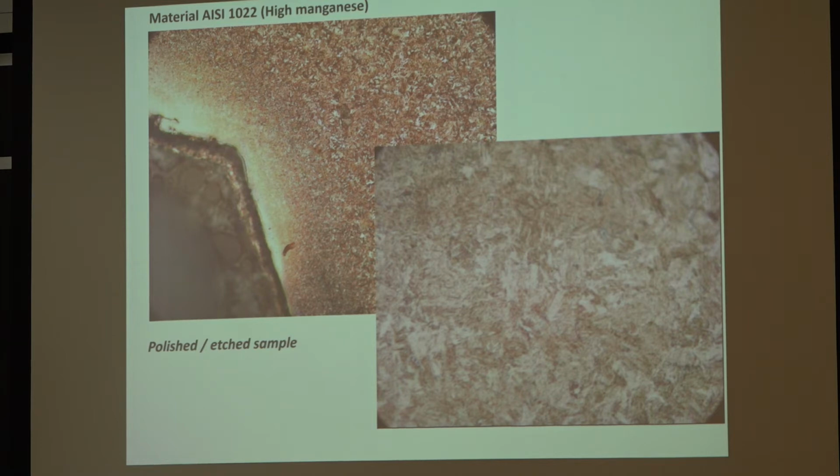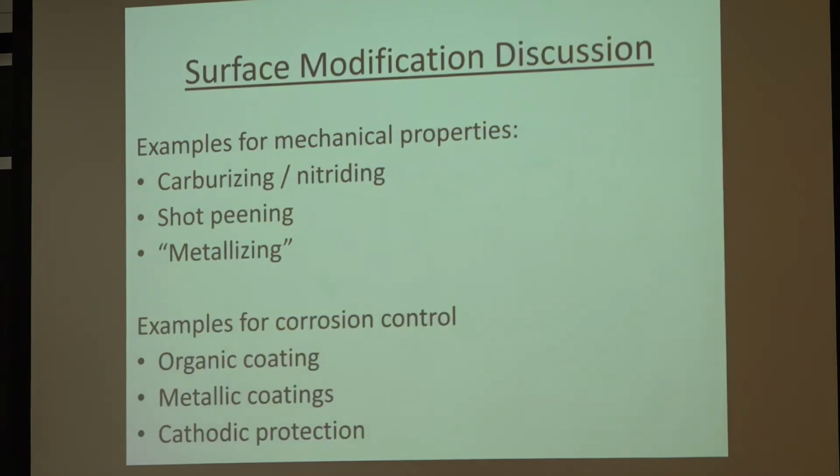And there are ways where you can do that heat treatment preferentially on the tip and not have it on the thread itself. That's a very, very smart way to do it, so you don't risk the crack initiation on the threads, but then it's more expensive. You have to engineer that so the carburization or the nitriding doesn't get to the structural part.